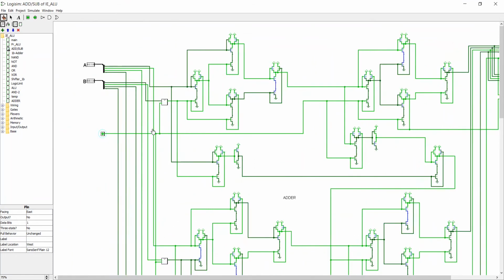The reason this circuit fulfills the goal of decreasing area is because I can compute the two's complement on the fly. By choosing mode 0 for addition and 1 for subtraction, I can instantly compute the two's complement and add that to A, thus doing the subtraction operation. This eliminates the need for a separate subtractor circuit, hence increasing overall area efficiency.